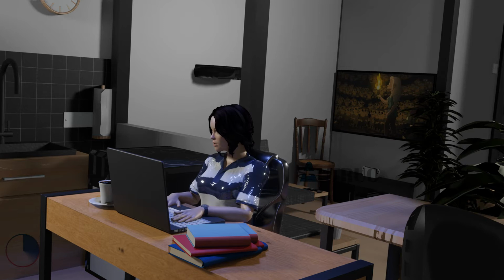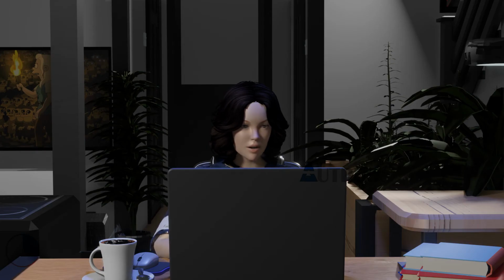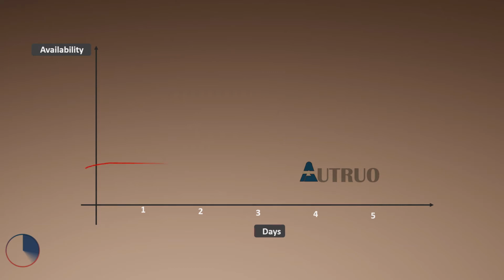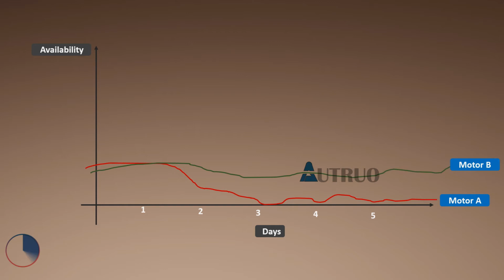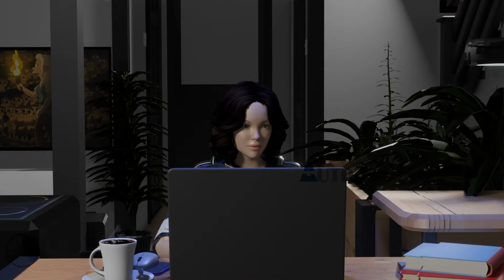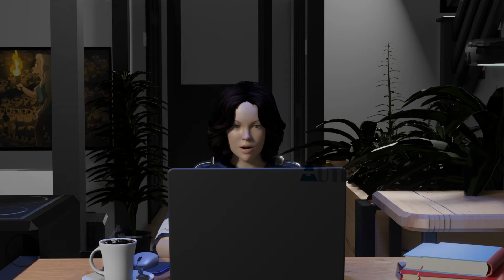Perfect. This is necessary because the frequent start and stop of electric motors will have a negative effect on the motors and some other connecting devices. Looking at this historical data, as you can see from the first graph, this motor starts very often and, from the data gotten, has a lesser lifespan as compared to the motor that starts and stops less often. From this data, this motor has a longer life as compared to the other motor. Again, the contactors will also be affected because of the frequent energizing of the contactors' coils.